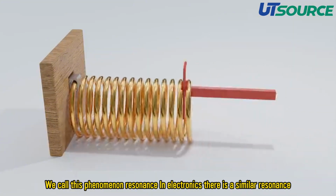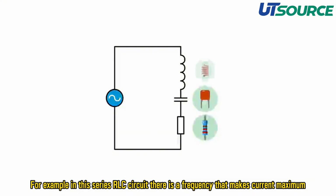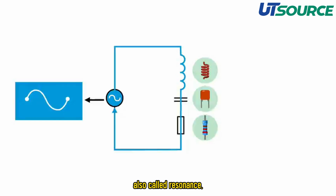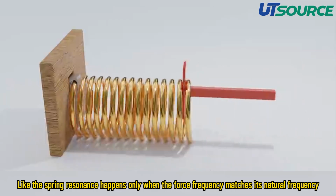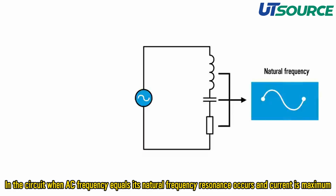In electronics, there is a similar resonance. For example, in this series RLC circuit, there is a frequency that makes current maximum, also called resonance. So what is this frequency? Like the spring, resonance happens only when the force frequency matches its natural frequency. In the circuit, when AC frequency equals its natural frequency, resonance occurs and current is maximum.